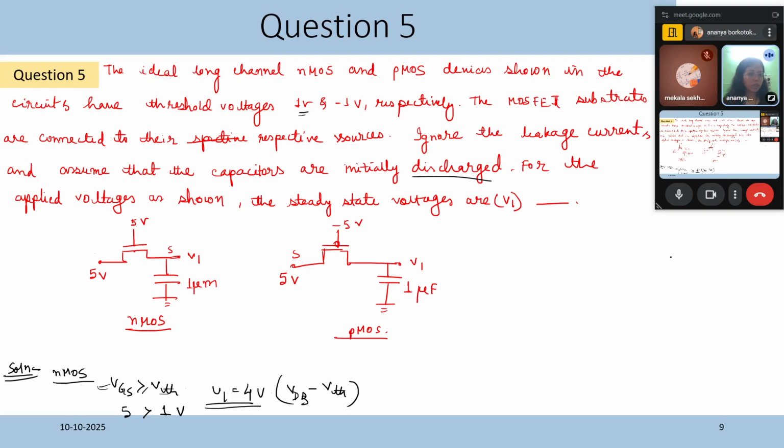That is why, if you remember, in a CMOS circuit we make these two blocks. Here this will be connected to VDD and this will be connected to the ground. The part which is pulling up our load will be connected here. Say if I'm connecting a resistor as a load, then the pull-up part of the circuit is made using PMOS. Sorry, the pull-down part of the circuit is made using NMOS. So NMOS is not a good pull-up transistor.